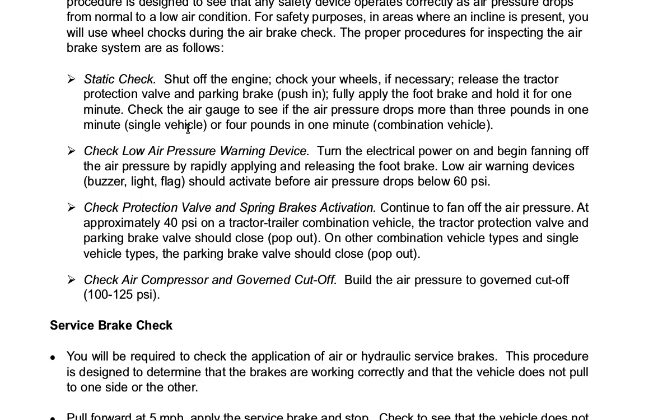Alright, static check. Shut off the engine, chock your wheels if necessary. Release the tractor protection valve and parking brake. Push in. Fully apply the foot brake and hold it for 1 minute. Check the air gauge to see if the air pressure drops more than 3 pounds in 1 minute for a single vehicle, or 4 pounds in 1 minute for a combination vehicle.